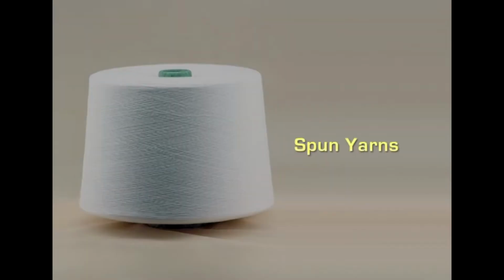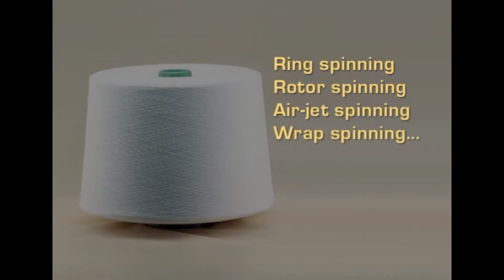So, when we take generally the characteristics of spun yarns, we can see that the fibers are mechanically assembled and twist is imparted to them, and it does not mean that they contain only one type of fiber, it can be a blend of different types of fibers. In fact, there are different methods of making a staple yarn, ranging from ring spinning, rotor spinning, air jet spinning, etc. And all these methods would produce spun yarns only.